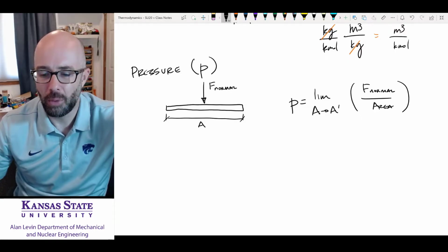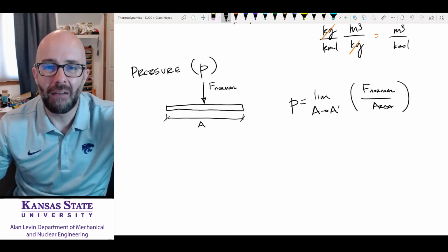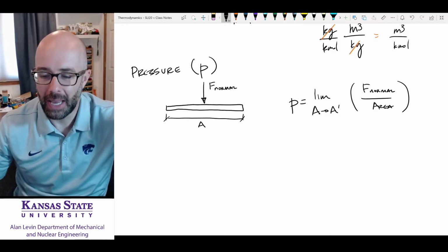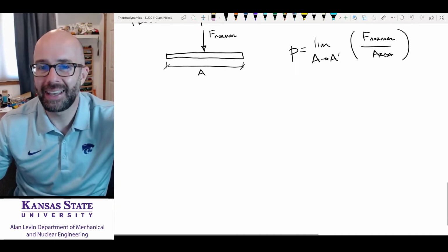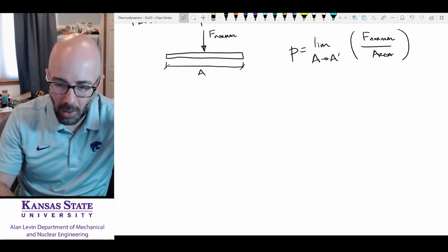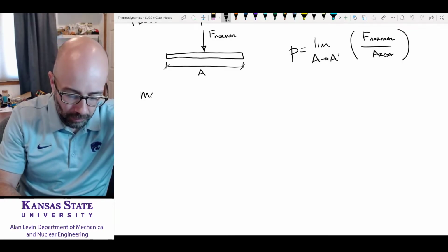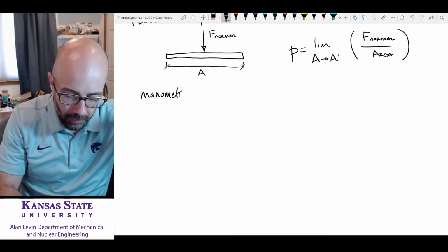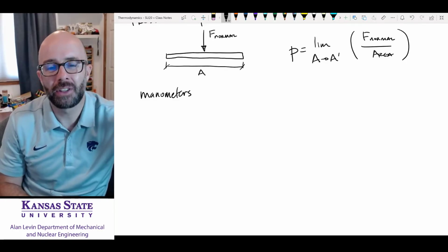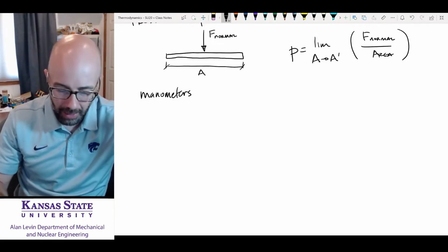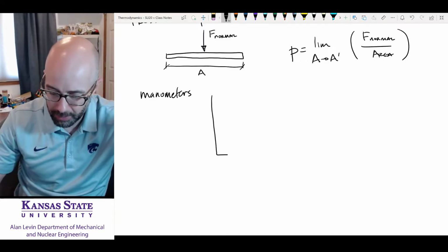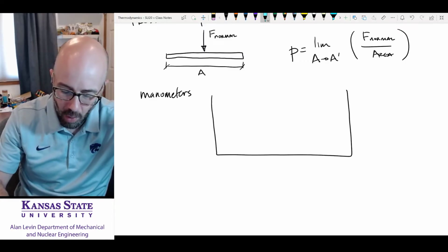I'm going to deal more with that pressure that you can measure and that value of pressure given to you by a pressure gauge, a Bourdon gauge, a barometer, a manometer, something like that. We're going to look at that value, but you need to know how to deal with those things. So let's talk about maybe manometers a little bit. And I'm assuming in physics that's some of the prereq material that you have coming into here. But let's say we have a tank full of water.